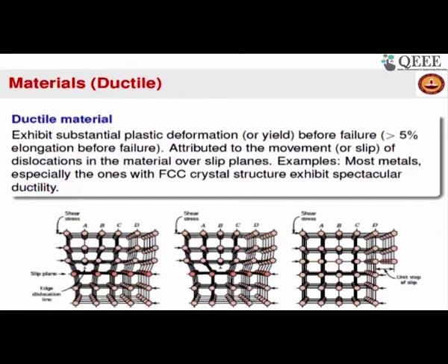there are different planes of atoms which are labeled A, B, C, D on slide number 16. Okay, this plane of atoms A is going halfway into the crystal, whereas in the remaining half there is nothing. It doesn't continue into the crystal at all. So this extra plane of atoms that is present is causing some sort of distortion to the crystal lattice.